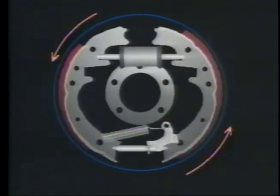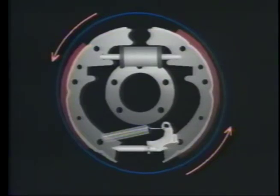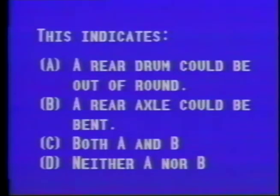In this example, the problem is narrowed down to the rear of the vehicle. A brake drum that's out of round could cause the brakes to pulsate. So response A is true. A bent rear axle, as indicated in response B, will cause the drum to wobble, which will also result in a brake pulsation. Therefore, the correct answer is response C, both A and B.